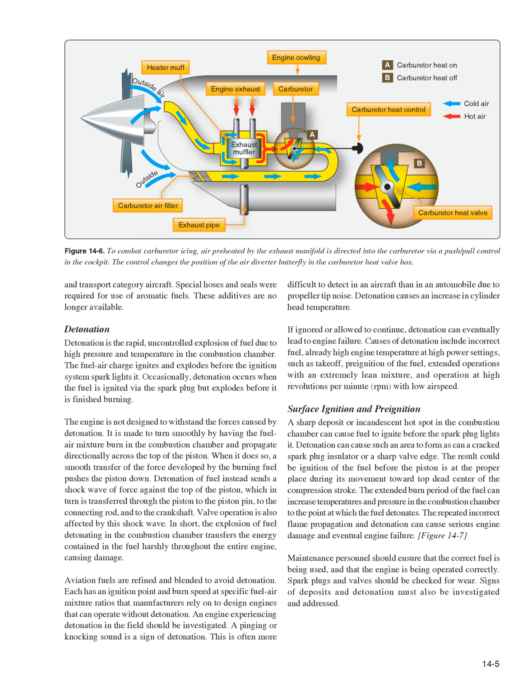Aviation fuels are refined and blended to avoid detonation. Each has an ignition point and burn speed at specific fuel-air mixture ratios that manufacturers rely on to design engines that can operate without detonation. An engine experiencing detonation in the field should be investigated.